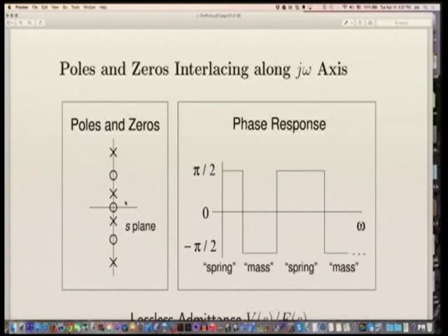It only reflects the energy back at you with some phase. So it's an all-pass filter, a little bit degenerate because of these zeros right here. To make it well behaved, you would move the poles just a little bit to the left, and the zeros would also come off a little bit to the left. Introduce a little bit of damping, and then it's almost an all-pass filter.